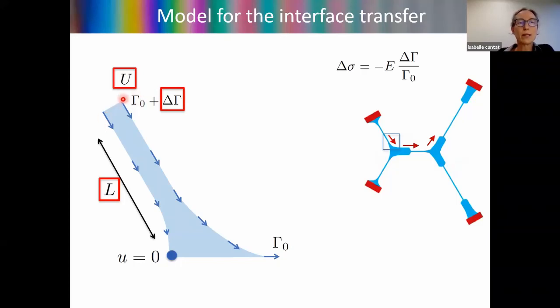This interface flows at the velocity u and can slide freely over the meniscus to reach the central film. But this interface, in contrast, has at the beginning the same velocity, but must stop at this point, which by symmetry is a point of vanishing velocity.